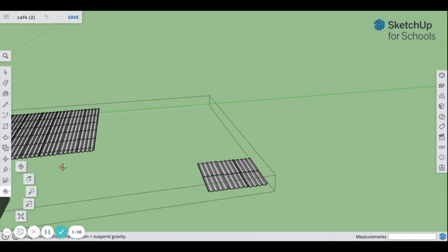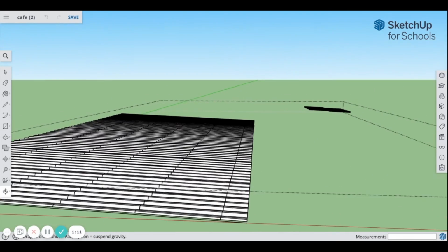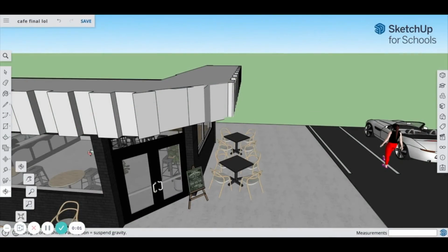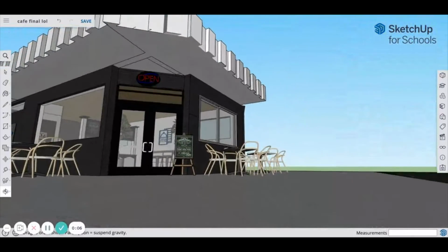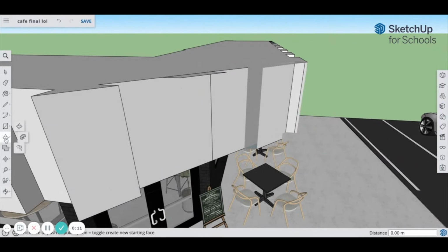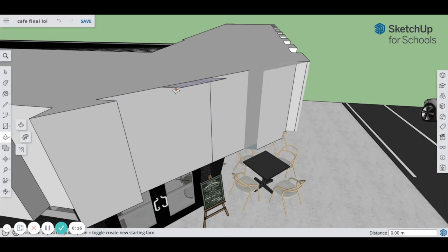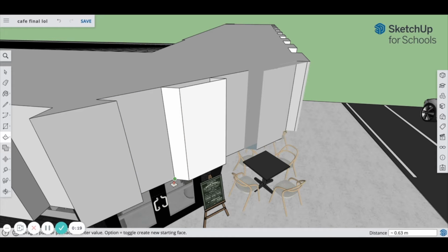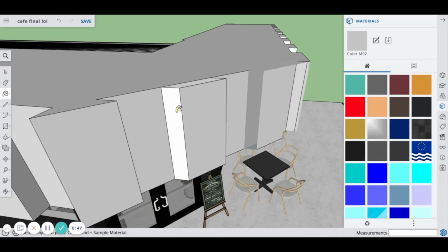Another issue I faced during this task was during the process of constructing my panel. I discovered that the panel would have to be on an angle, as the north and east point of the cafe didn't meet directly, as I had my door on an angle between these 2 points, and for the panel to cover an equal space I needed to follow the same angle as the door, or else the panel would be too far out. This was overcome as I drew the line I needed the panel to sit on and started to sketch the panel onto the line, where I then used the push-pull tool to select this and pull down until it was level with the other side. I then repeated this process until I covered the frontage.